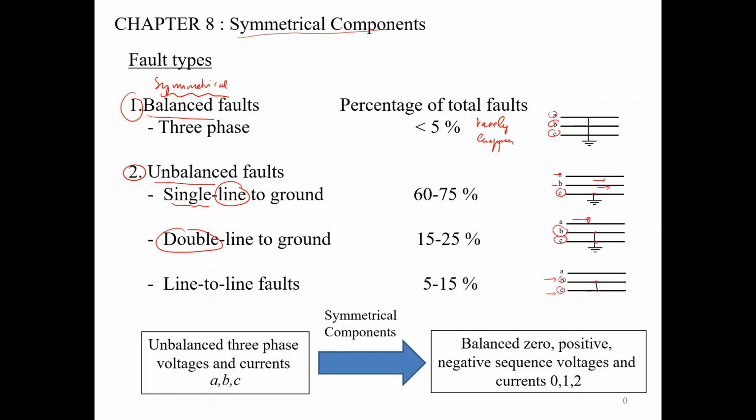So why are we interested in learning the symmetrical component? Because the symmetrical component will be the tool to analyze unbalanced voltages and currents. We have learned from several courses in basic power system that the main assumption we have made in learning three-phase power systems is that the three phases are balanced.